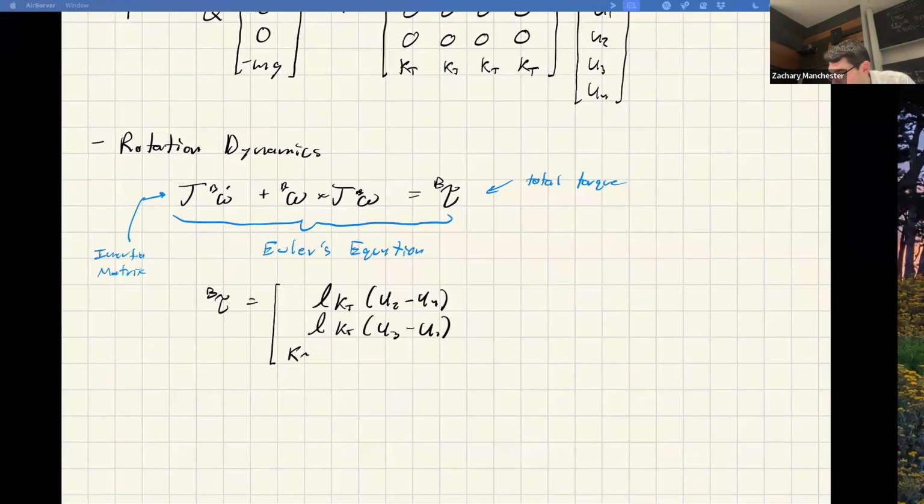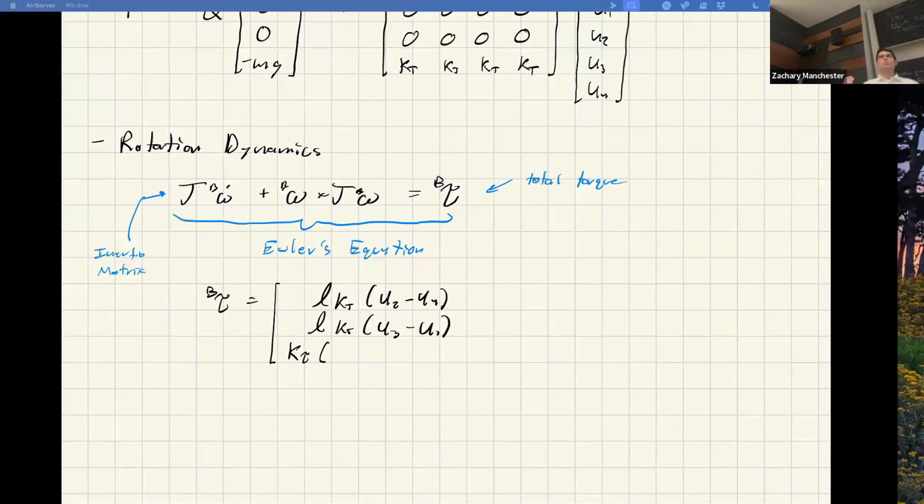And that's actually what gives you yaw control authority on a quadrotor, that prop torque. The subtle thing is you need those props to spin in alternating directions so you're able to control the yaw and cancel out those prop torques so it's not spinning all the time. So we're going to have alternating signs in here. This is a detail that might vary between quadrotors and models, and you should check the conventions, but we're just assuming it's right-handed, positive, and alternating as you go around.